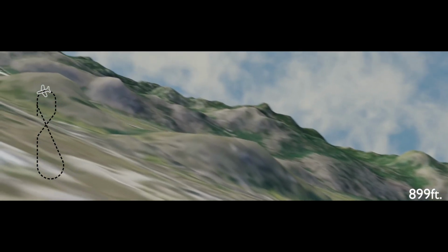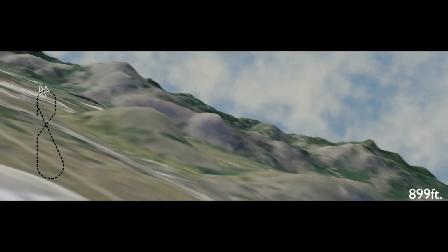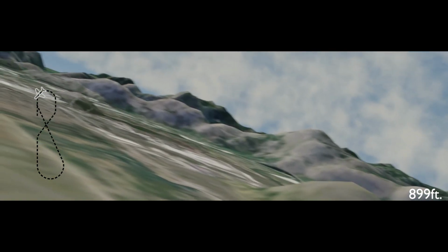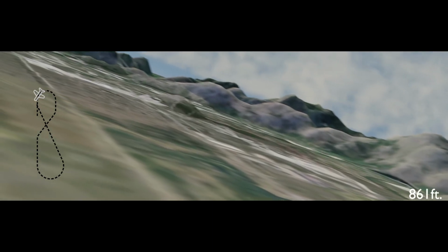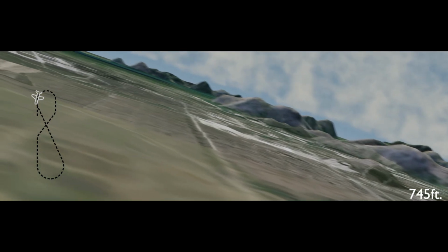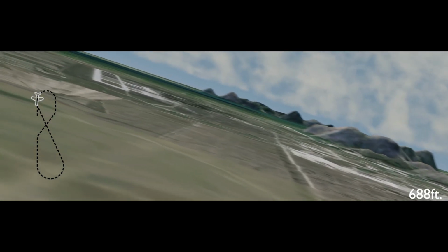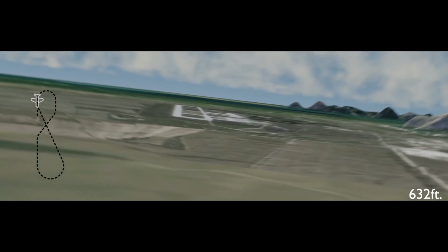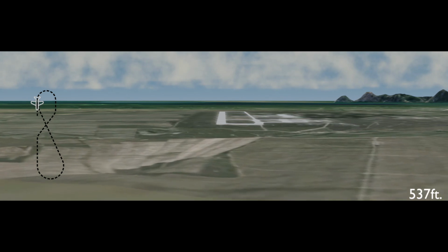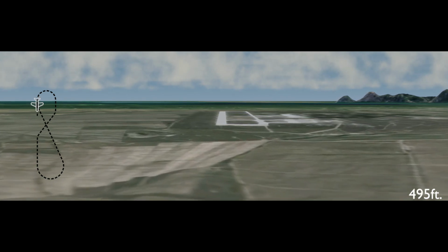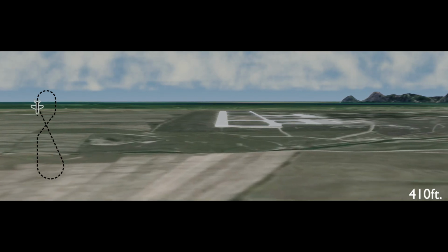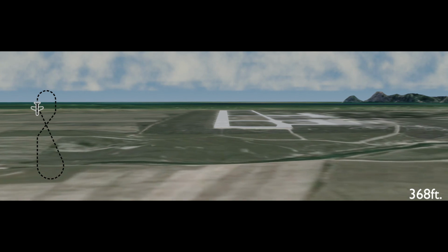We're going to fly the final approach with a standard 3-degree glide path. Our MDA is only 780 feet above the runway, so we'll descend from MDA when we're about 2.5 miles to the landing threshold. We roll out on final approach north of Podgorica VOR with about 1.5 miles to touchdown. The runway perspective on 18 is different to 36. We're flying a 3-degree approach and there's a slight downslope on the runway.